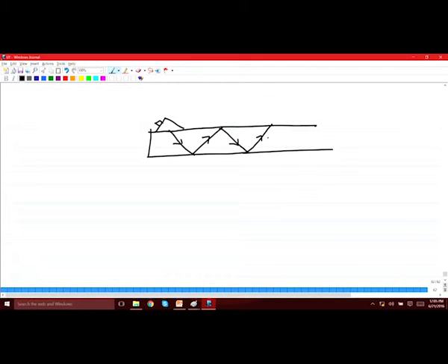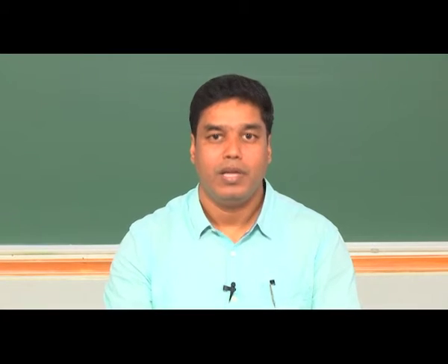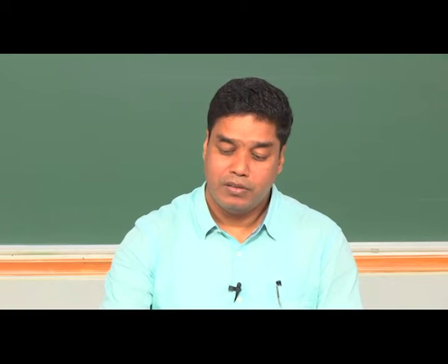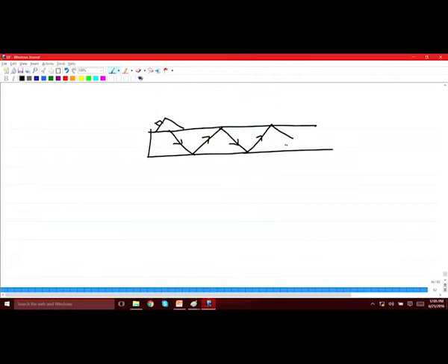Okay. So, that means the back wall echo that you see in case of a normal probe, you are not going to see that in this case. Okay. So, this echo will come back only when it encounters an interface which could be a discontinuity or a defect. So, when it encounters a reflecting interface, then it is going to reverse the direction and follow the same path and will come back to the probe, and that is where you get an echo from a discontinuity which is present in the path of this beam, which is going in a zigzag manner like this because of that incident angle.